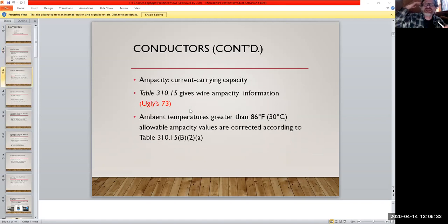And again, like with everything, we look at ampacity, and it's always our ability to deliver. You'll see these ratings on a lot of stuff too. Transformers will have it, and you'll always see it specified not in watts, which is actually the power that is delivered, but for ampacity, you'll typically see it listed as VA, volt-amps. That means the maximum that this particular thing could do. So if you see that designation of VA, that's what it's talking about relative to the device or instrument that you're looking at. And we do have a table within the NEC.